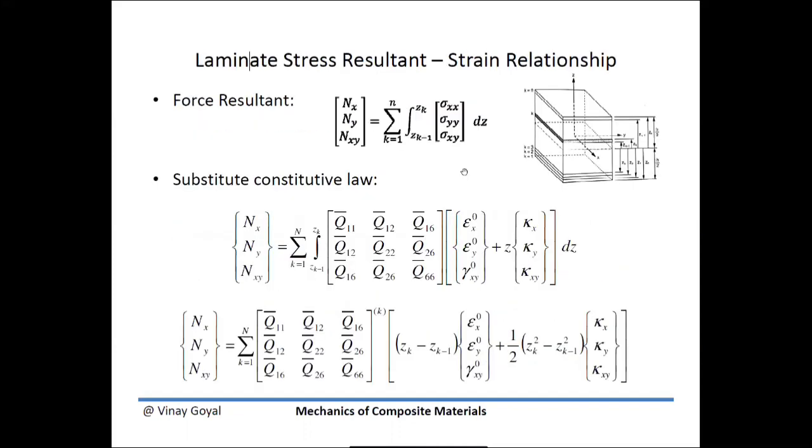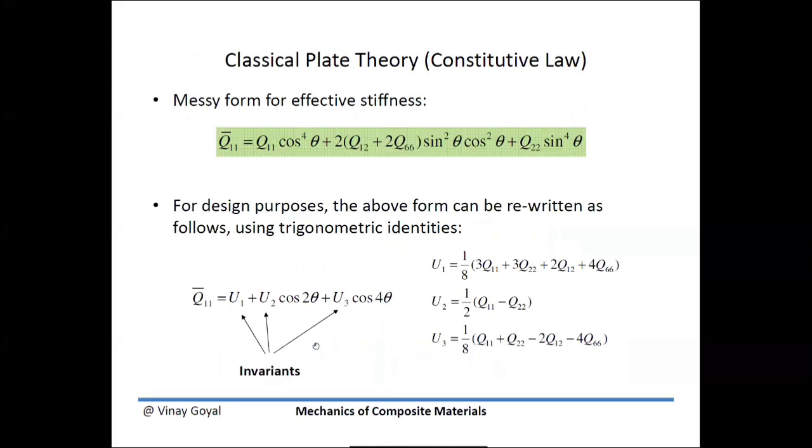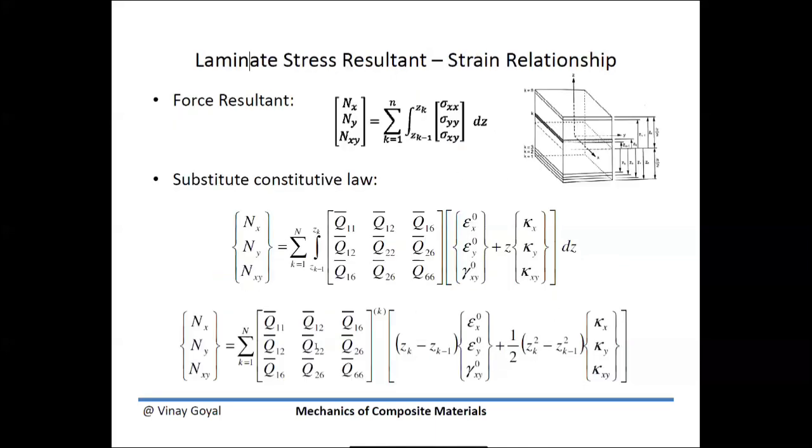Okay. So when I go here, I realize that this integral over the kth ply has sigma xx, sigma yy, sigma xy. This here is the Q bar matrix that we discussed times the strain matrix that we discussed earlier. Are we done? Substitute the stress for that. Now notice that this strain is the strain through the thickness of the whole thing. But we found earlier, and you're welcome to pause the video and look at your notes, that strain is equal to the mid-surface strains plus z times the curvature strains. So this is what we got there, and I can go ahead now and integrate.